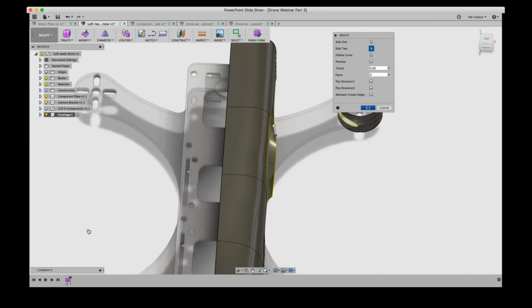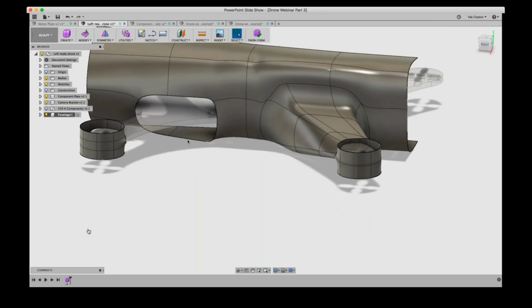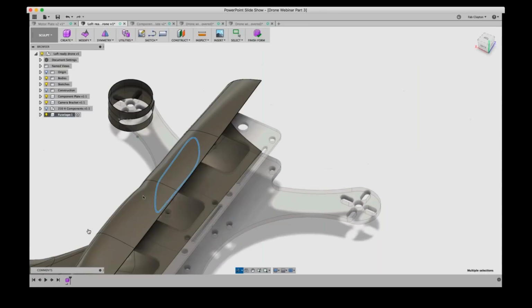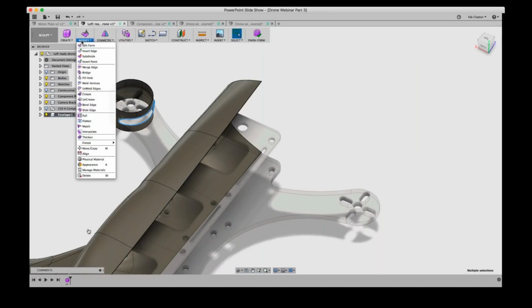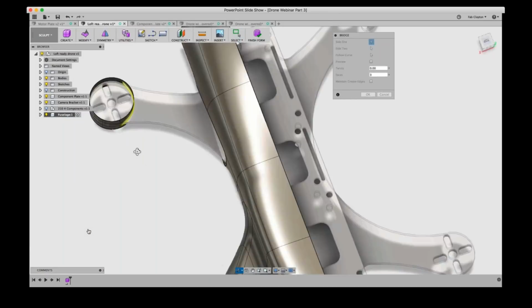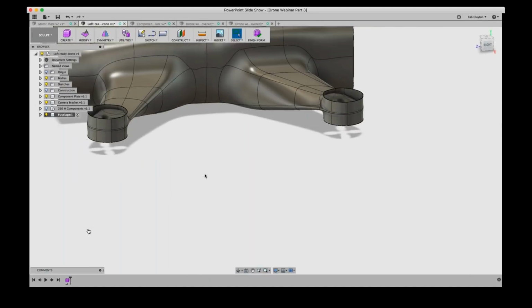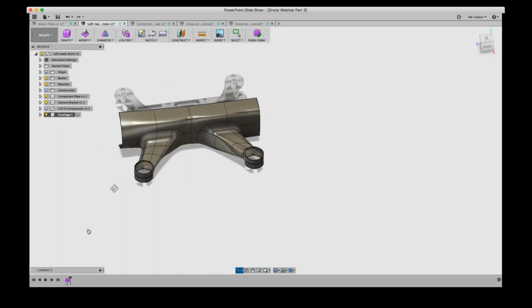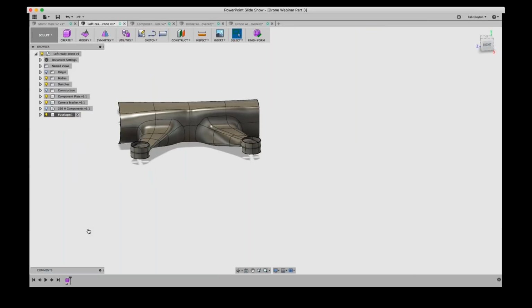to create an opening to protect our booms, which are these arms that hold the motor of the drone. And that's it. You select one side, and the dialog that opens asks you to select the second side, where it says side 1, side 2. Double click to select the whole thing, and then you have both sides, okay?